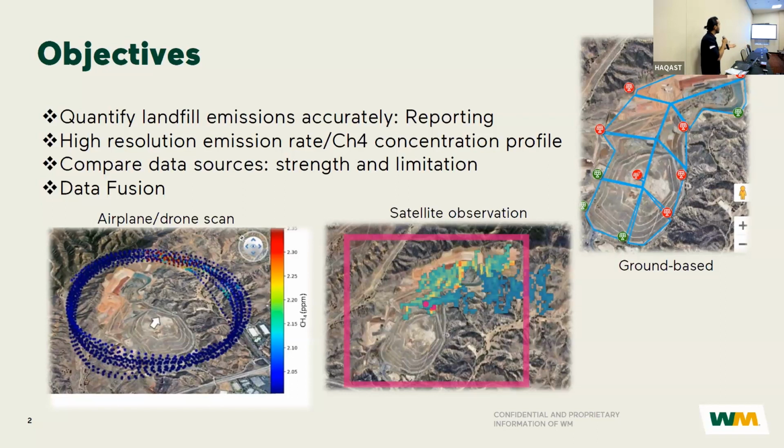It's really hard to translate the concentrations on the ground level, specifically for landfills, because they're not point sources, and usually they're an area source. So the figures that I've put on here are the 3 different data sources that are usually used when you're having an air quality problem, let's say. My background is from air quality. So when you have air quality fusion, you usually have multiple data sources that each have some problem. For example, the ground-based data that we have there, this is the sensor grid that you see, different boundaries, different components of that landfill on the right top.